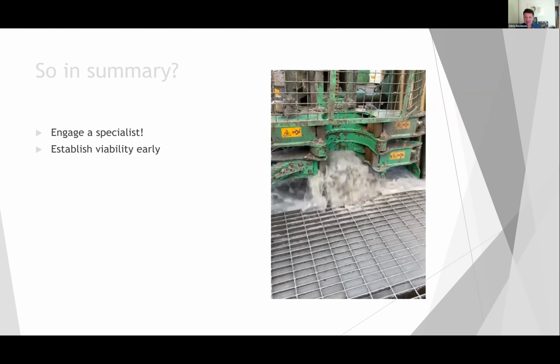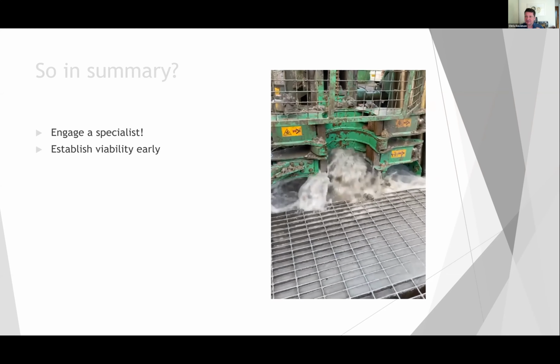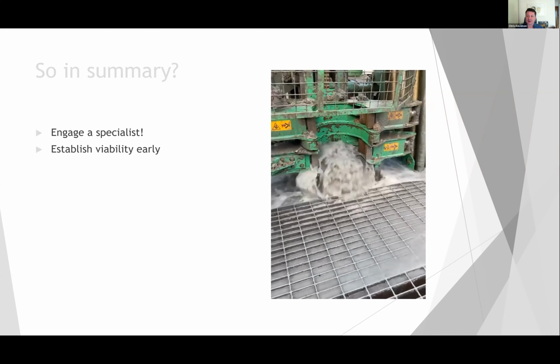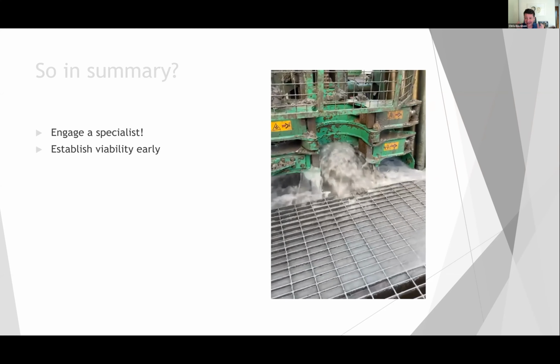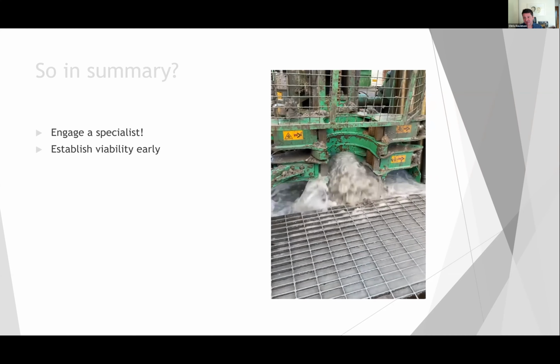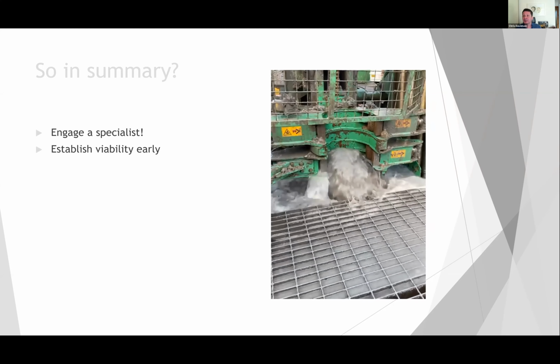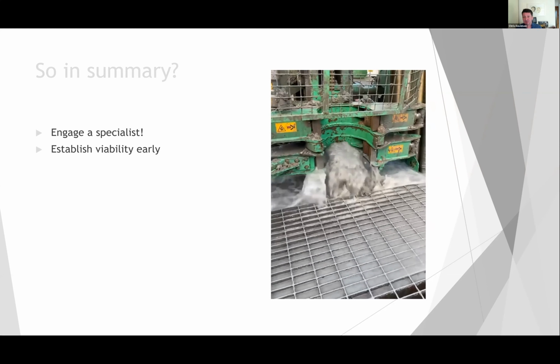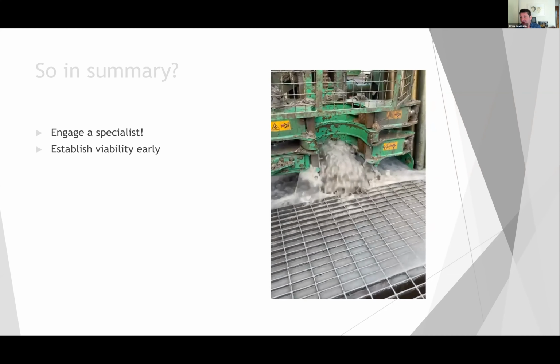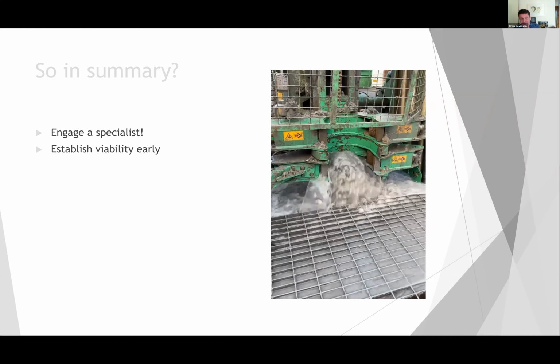The second thing that I would get across is establish your viability very early on in the project cycle. So get that geological analysis done and work out, is it even feasible to get 20 litres a second in that part of the UK? Because if you don't have a viable scheme, it's not worth proceeding with.